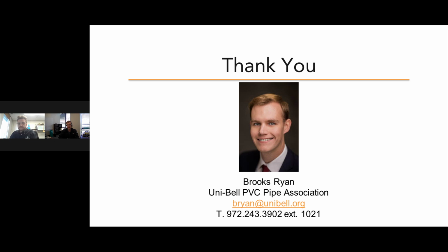Our recommendation historically has been to treat the cyclic life of PVCO the same as for PVC of corresponding pressure classes. We do expect it to have, based on some European studies and Australian studies that have been done, a higher cyclic capacity for PVCO, just because of the higher modulus of elasticity and higher tensile strength. But we can't definitively say that till we have concrete data, and so that's the point of the testing.